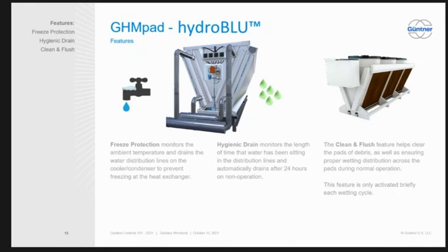So on the Belimo valve, there's a polarity switch where you can just swap it. If you open up the cover, and I think I actually have a Belimo valve right here, I don't know if you can see it or not, but there's a little polarity switch right in there. You could take a flathead and change it, and what that'll do is, instead of being closed, it'll open the valve.